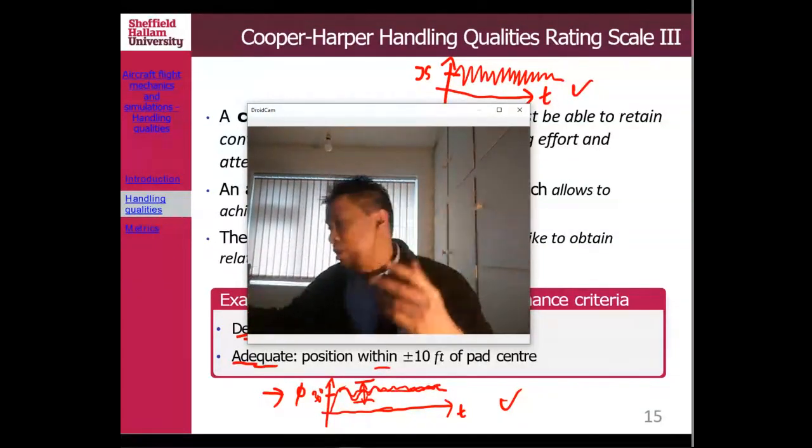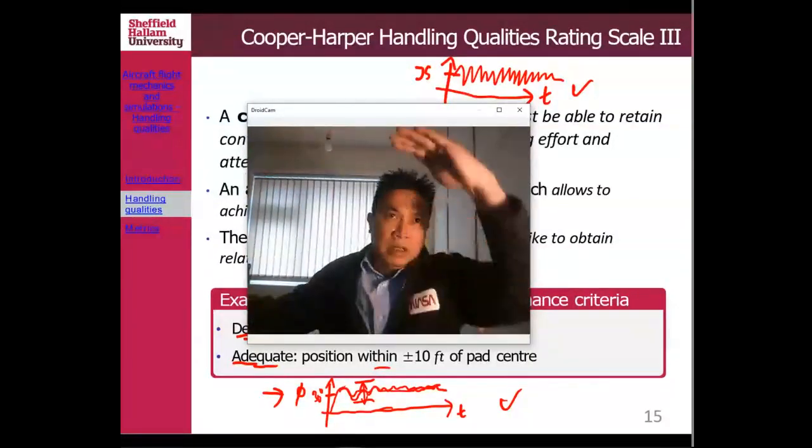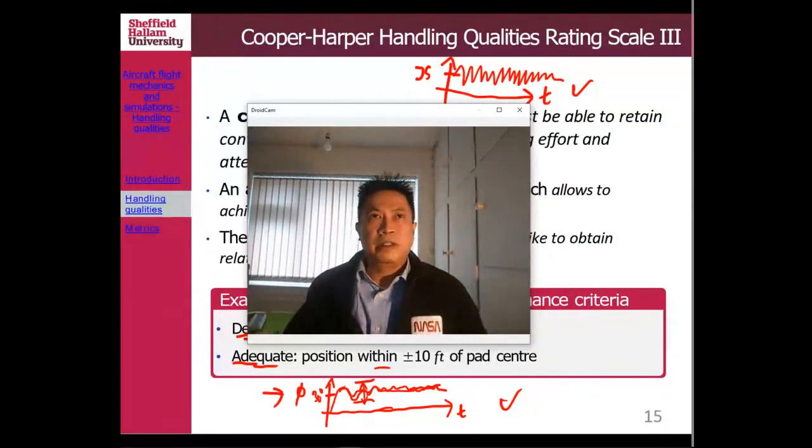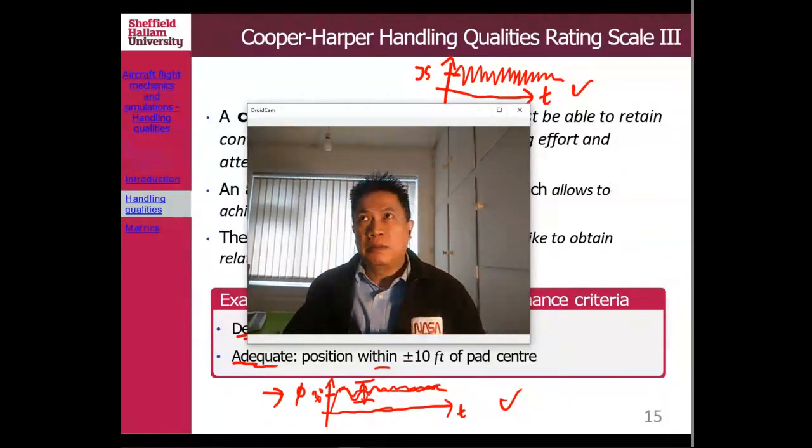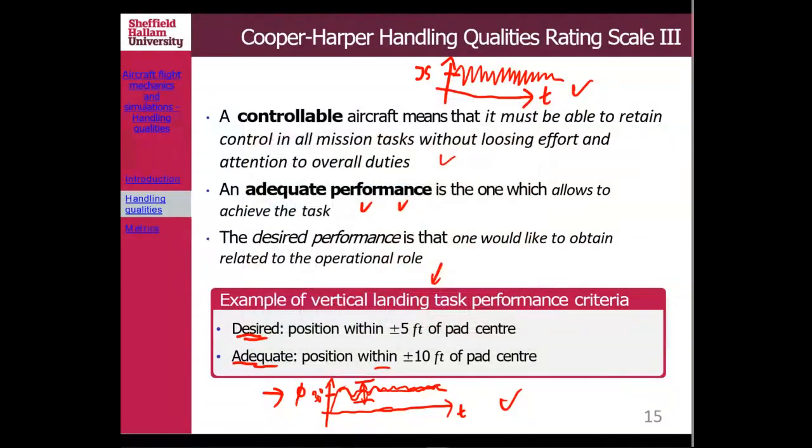So you might need to also check your altitude reading, whether you drop your altitude or even increase your altitude. I think that's perhaps a better way to make sure that the performance is being achieved, right? The task has been achieved. Because if you drop the altitude, it means you don't complete your task properly, because the task asks you to hold the bank angle at 30 degrees without slipping or skidding.